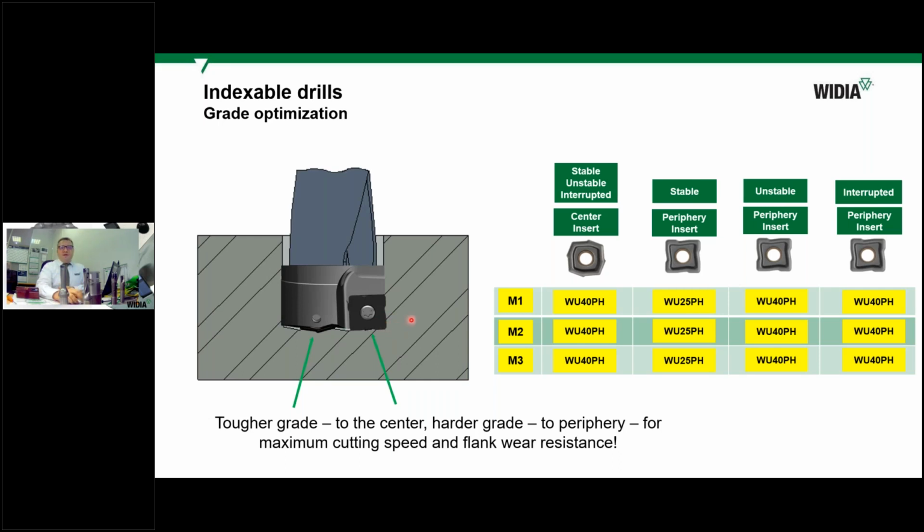So for example, we chose 150 meters per minute, but the smaller the diameter, the lower the cutting speed. Unfortunately, we cannot vary the number of revolutions every time, so it's constant. That's why near the center we have a cutting speed of about 0, or 20% or 50% at different points of the diameter of the drill.